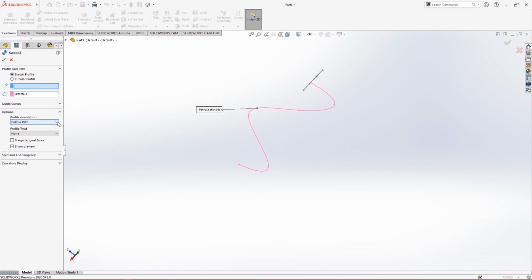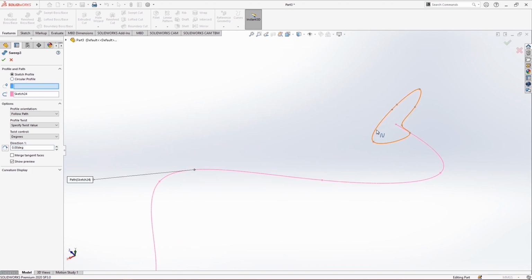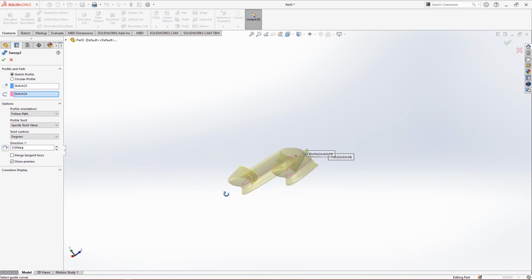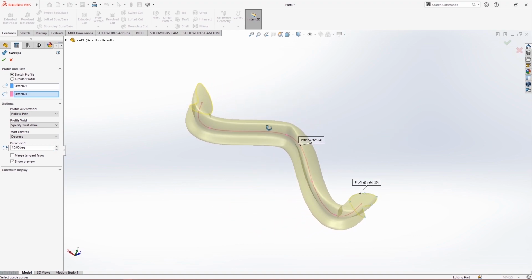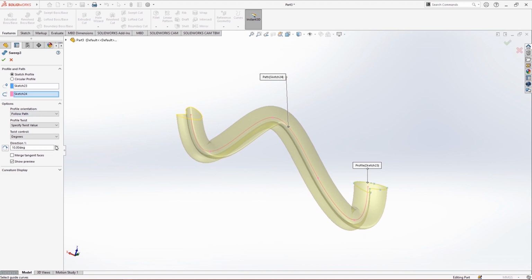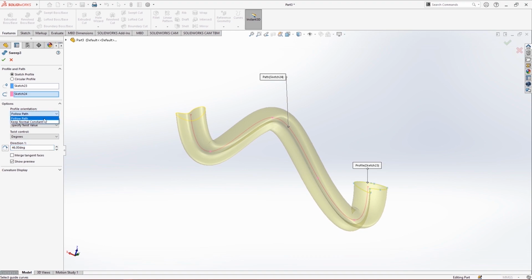And other options are like you can add some twist values here. Yes, so you can also add twist values from here, and you can see there are some variations in twist. You can see it is rotating here as I'm changing the values. So make it like 50 or 46 degrees. It has changed quite a bit, and you can do a lot of changes.